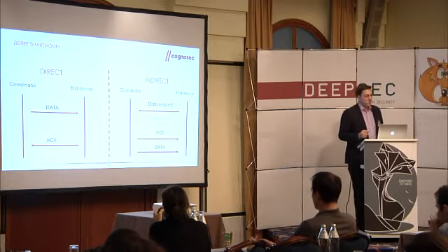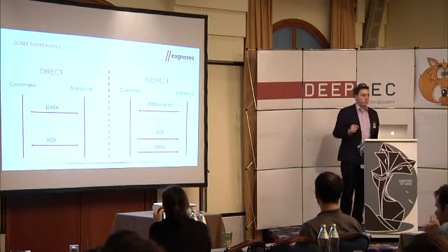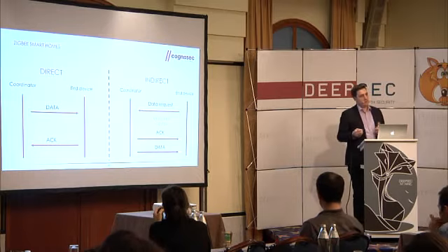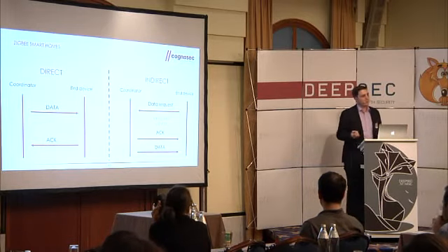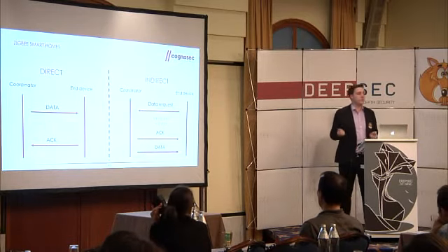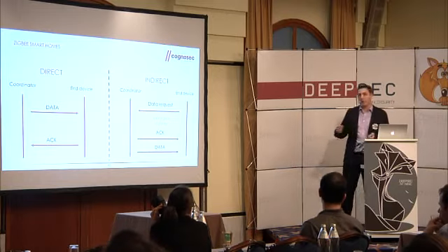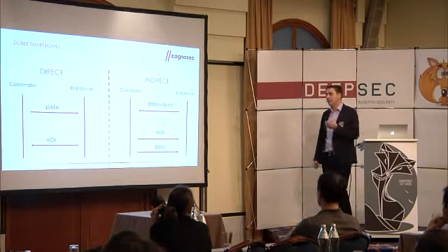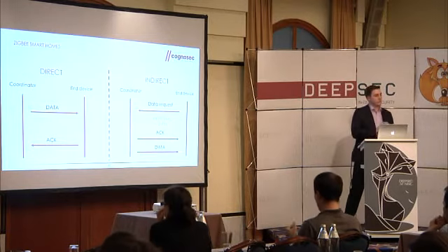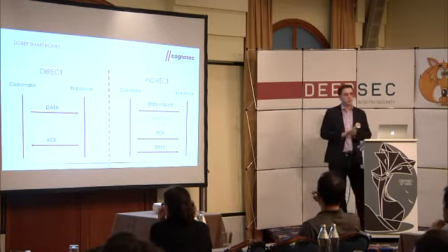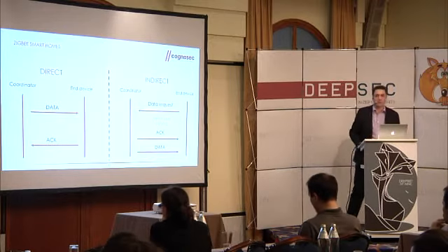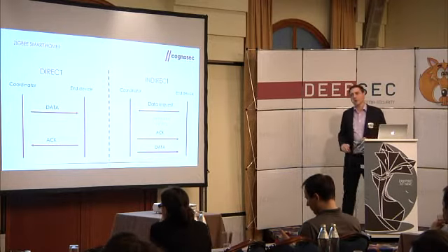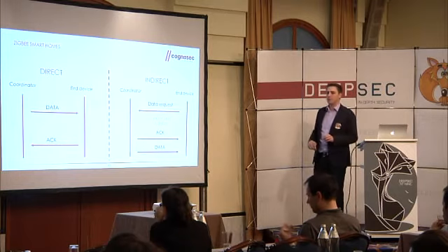So in the real world, there are ZigBee devices with power supply, which means the ZigBee router. The receiver is on all the time, so you can send messages there all the time. That's called a direct data transfer. This means you just send your data there, you get an acknowledge, okay, received, very good. But as we heard, ZigBee is built for low power devices.